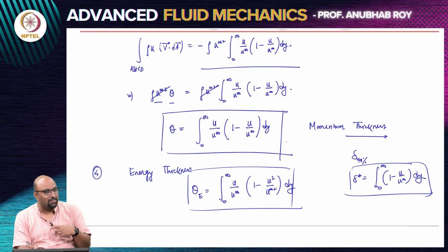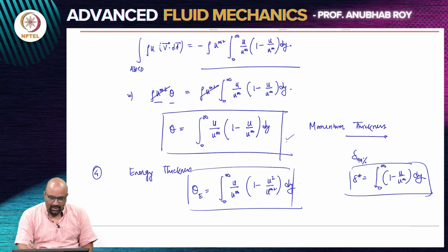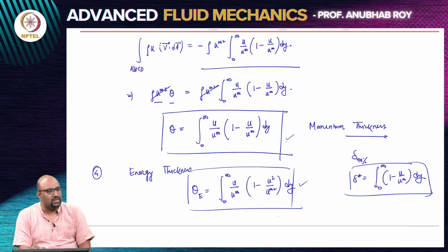So, these are indirect measures, not direct measures of what the thickness actually is. The displacement thickness gives you more of a physical picture. If you were to put dye tracers in a steady boundary layer, the path taken by the dye would show a deflection, and that deflection is in some sense related to your displacement thickness. But the momentum thickness and energy thickness will also be closely related. Once you know the velocity profile, you can compute any of these things.